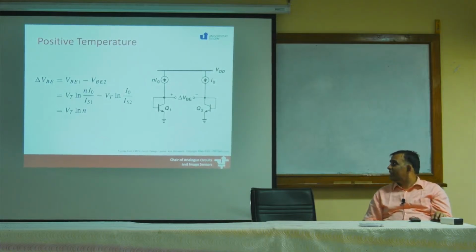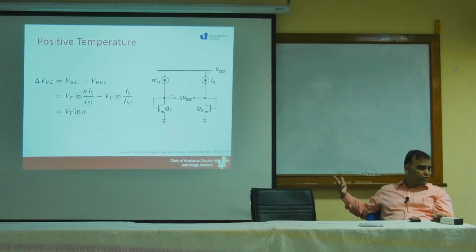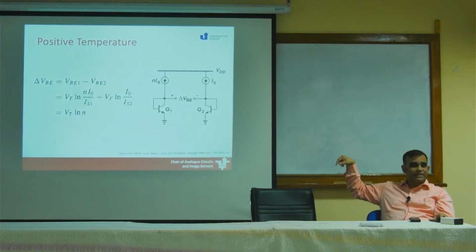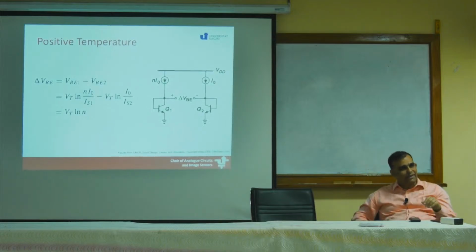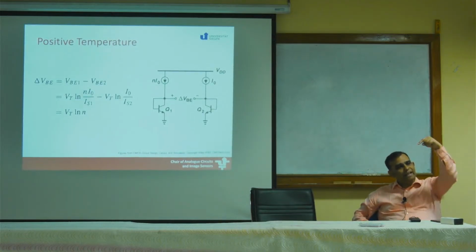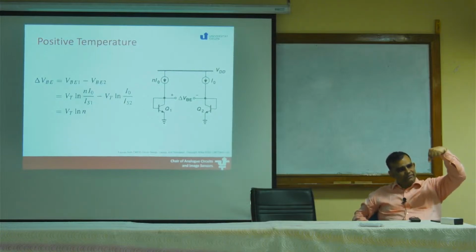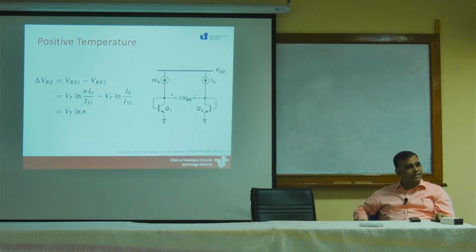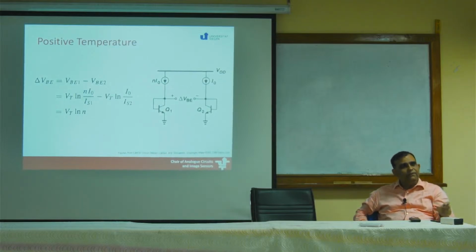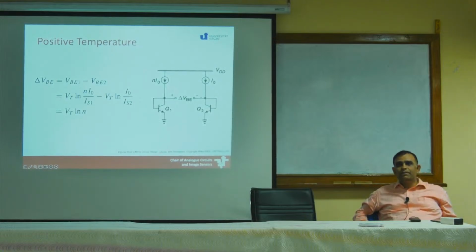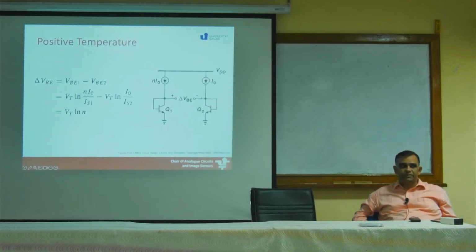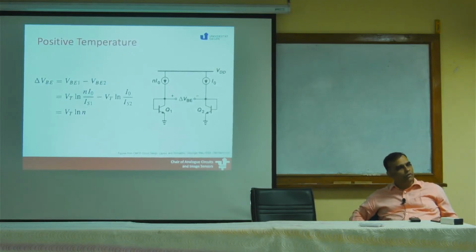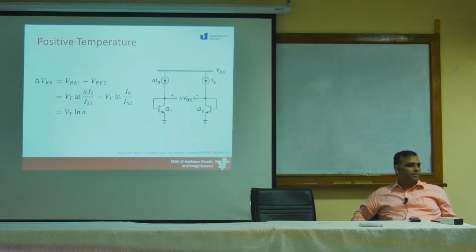So, by doing a circuit like this, where we force, and we can do it two ways. We can either make the transistor have n different transistors in parallel, or I feed n times I current in that transistor. So, current or voltages similarly we can use. And then if we take the difference between the voltages in these two circuits, this difference voltage between these two will be absolutely proportional to temperature. It will not have those funny log terms, it will not have those complex comparators.